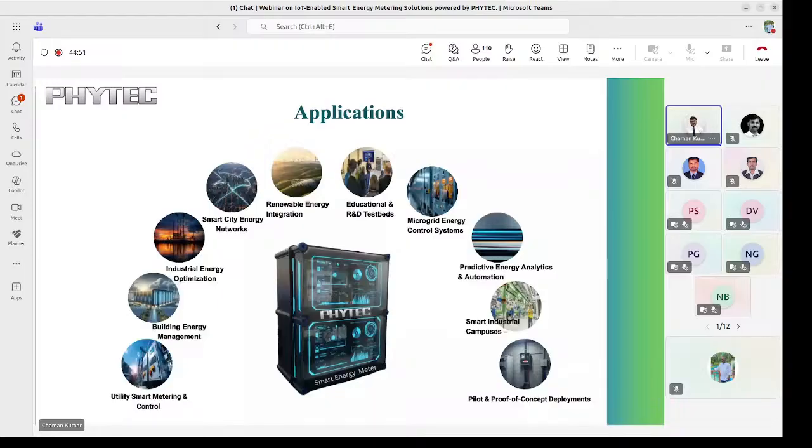And if you see the block diagram for this one, for power it needs 3.3 volt, and for flashing the firmware, we have to flash through the SWD, serial wire debug flasher. It has both external and internal antennas available to send the data through the RF module. Then for interrupts it has GPIO, and it has UART, universal asynchronous receiver transmitter.